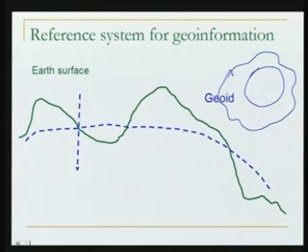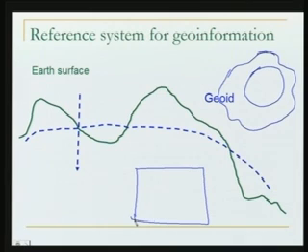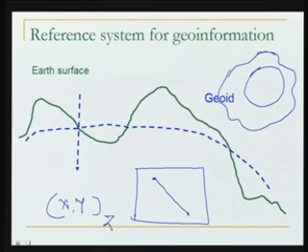Now this shape of the geoid is not mathematically defined. So even if we project our points onto the geoid, we do not know what is happening in between. In the case of our simple map, each and every point is defined. You take any 2 points, you can measure the distance between them, because this is a mathematically defined plane. But that is not so with the geoid. So basically, for making x, y measurements, or planimetry, we cannot use the geoid. Let's look into the height. Can we make use of the geoid to measure height?